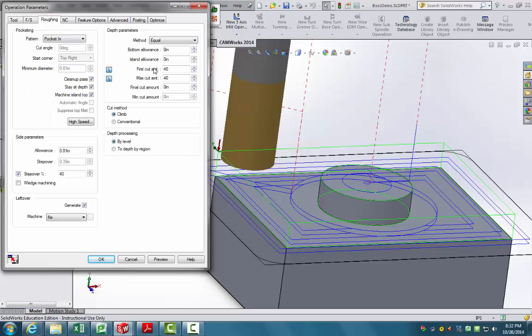Going to the roughing, we can see we have a certain amount of cutting in Z. We're leaving an amount of allowance for the contouring application, and we have a certain step over, and we can change these as we want. So I'm going to increase this step over to be about 60%. This means it's going to take fewer cuts to finish this.